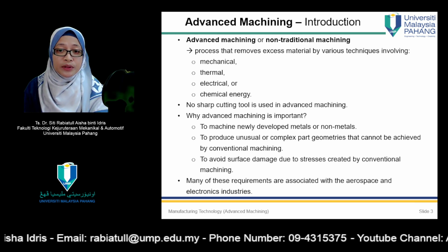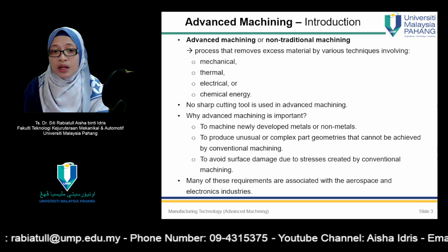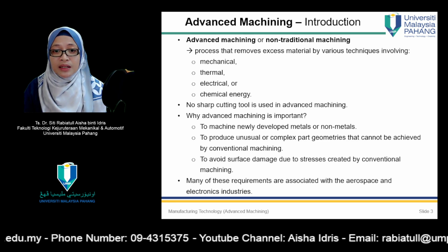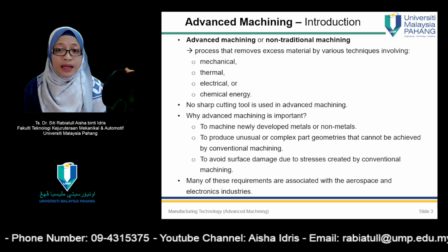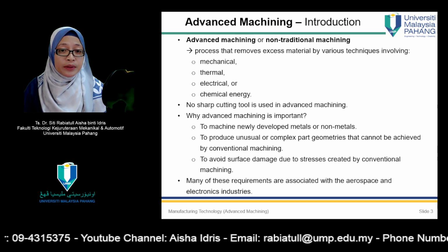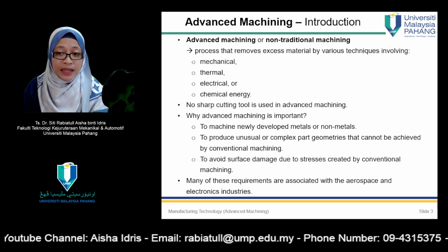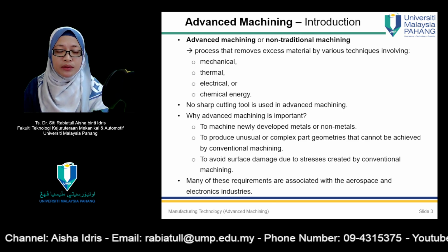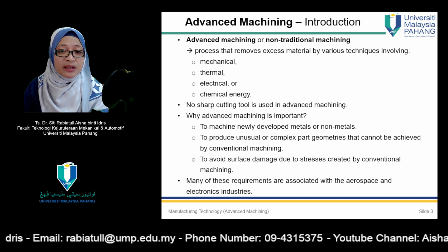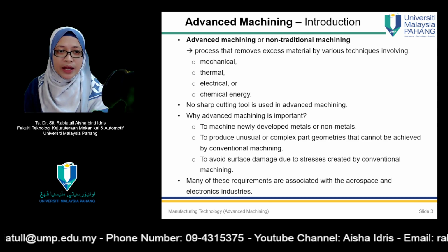The non-traditional processes have been developed since World War II, largely in response to new unusual machining requirements that could not be satisfied by conventional methods. These requirements and the resulting commercial and technological importance of non-traditional processes include: number one, the need to machine newly developed metals and non-metals. These new materials often have special properties like high strength, high hardness, and high toughness that make them difficult or impossible to machine by conventional methods.